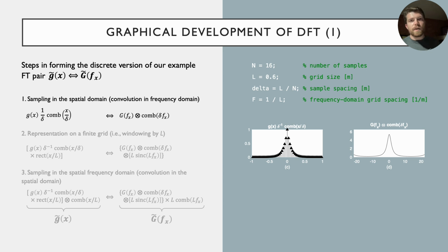In this example, we start by sampling the spatial domain, and we know that this causes aliasing in the frequency domain, and we can just barely see the effects of that in the far right image, as the convolution creates an image just outside of our axis limits.